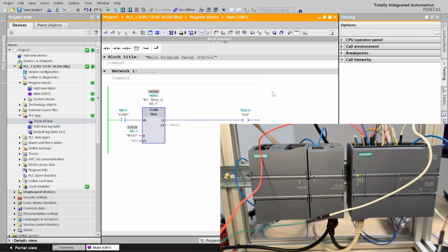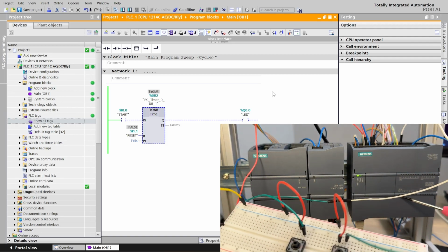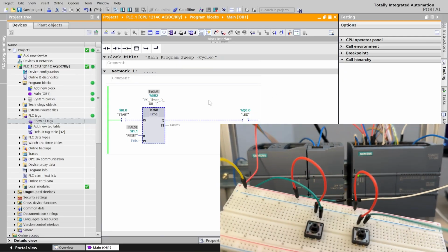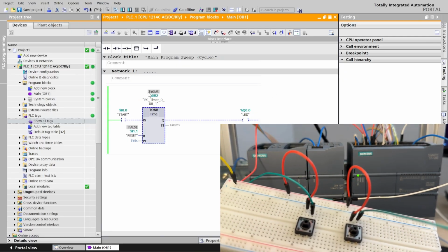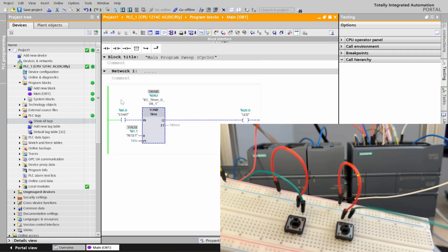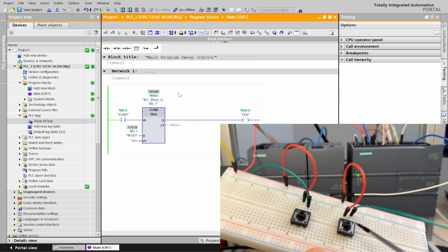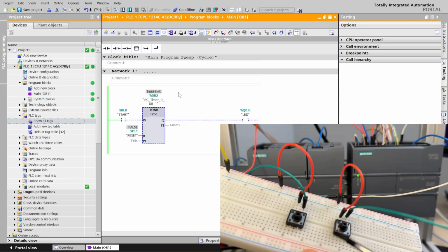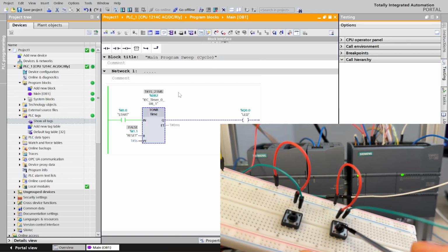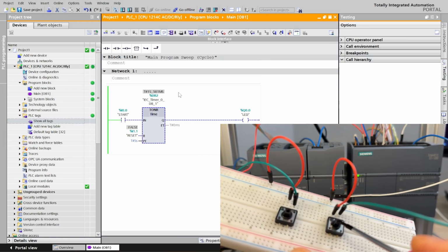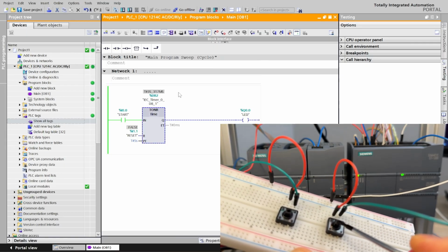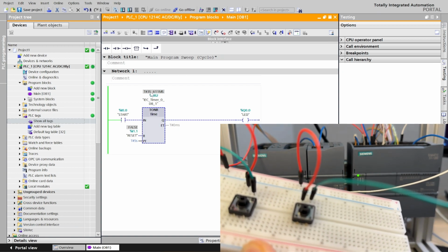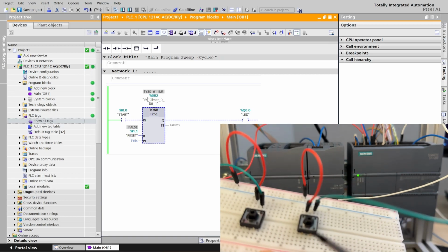And let's go demonstrate. Now here is our output, right? In this one here. So I press it. You have a look at the TIA portal also. Here it will show how many seconds the input is on. So I press it, for example, let's say almost 1 second. I press it again. I press it, I can hold it for, let's say, 2 seconds. You see that at 3 seconds, it is remembering. Every time I press,